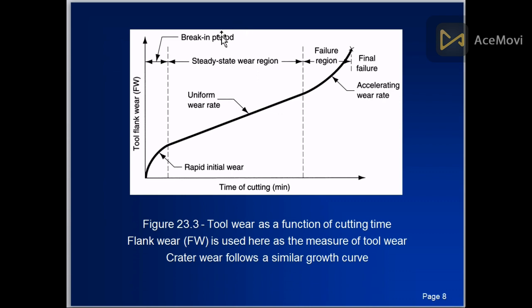Break-in period. This is a graph showing the tool flank wear related to the cutting time. Initially the wear is more because the tool is new, and we notice some rapid wear. But as time increases the wear rate is reduced, and at the final stage the wear is again high with respect to cutting time.